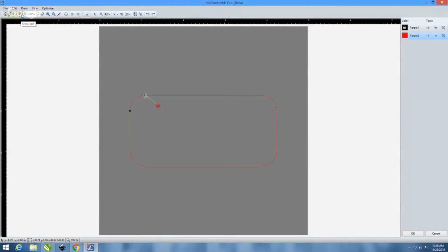Next, you can show usually, John, if you're cutting a piece of acrylic and the laser starts on the line, you have that tiny little blob. So you want to start it from coming in, right? Yeah. So Anthony, that's under draw, and you can do lead in there. So just up on the top menu, click draw. Oh.